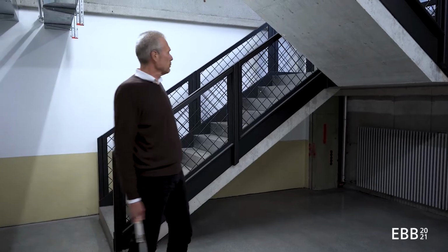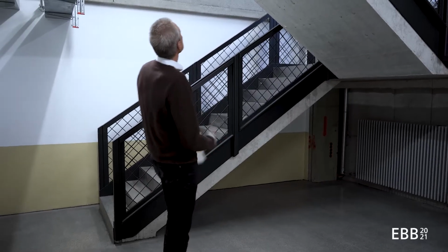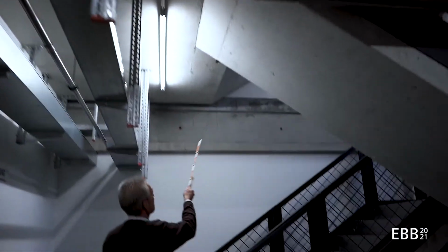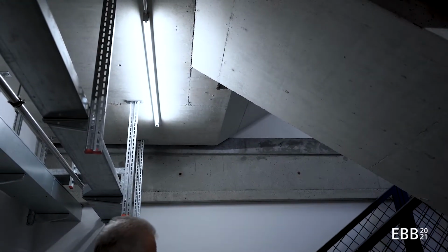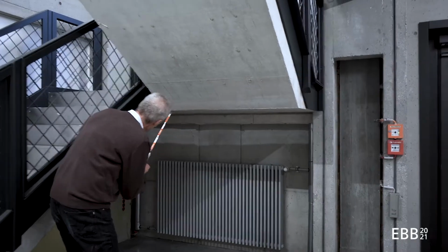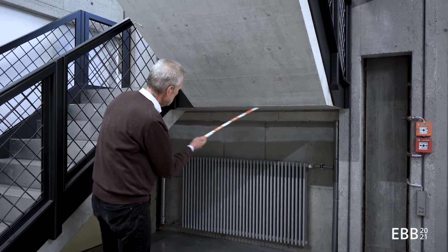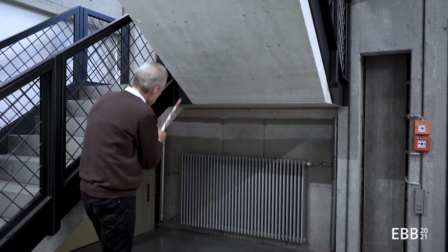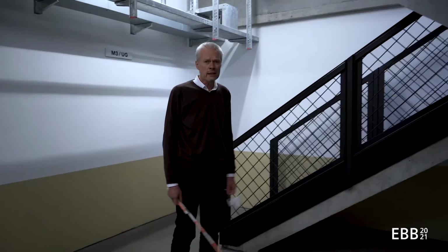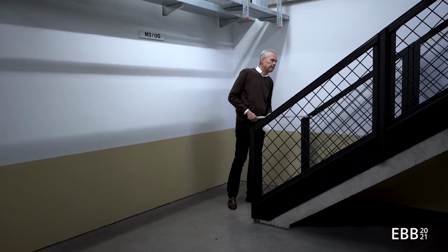So here I'm next to a rather badly designed staircase. Why is it badly designed? Because you can see that from below, here bottom up, very nervous knuckle line. And here for the landing, very nervous knuckle line. Knuckle line being this change of direction, the other change of direction, and here the eye of the staircase. Why is this so? Because we don't have enough space for the staircase. And come with me.